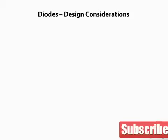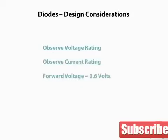As with all components, we must respect the physical limitations of the devices we are using. We need to know what the voltage and current requirements will be for the circuit that uses the diode, so we can select a diode that will withstand the maximum voltage and current ratings. It's a good idea to select an ample safety factor. Always observe and respect the maximum voltage and current ratings. Diodes need a minimum voltage to conduct in the forward direction. Typically, this is 0.6 volts. You need at least this voltage for the diode to conduct.